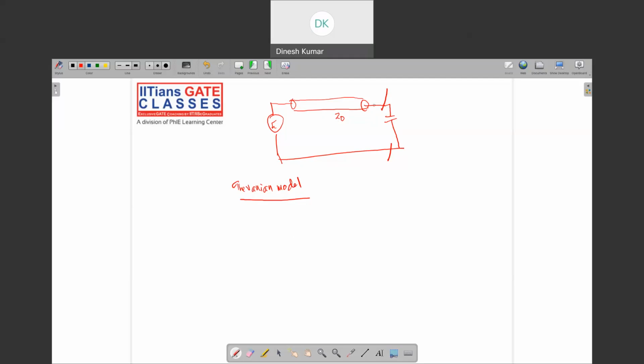If you make this open circuit and look at here, the first instant what we see is 2E, because this is basically an open circuit. What is the voltage at this particular point? It will be what is transmitted after the reflection. The reflection coefficient is basically 1, so the transmission coefficient is basically 2. That means we see 2E. If a person looks at this particular point, the voltage he sees is basically 2E. That will be the Thevenin voltage, 2E.